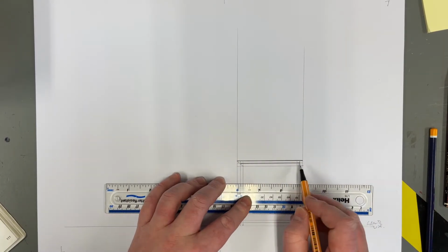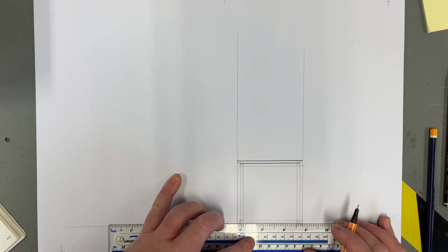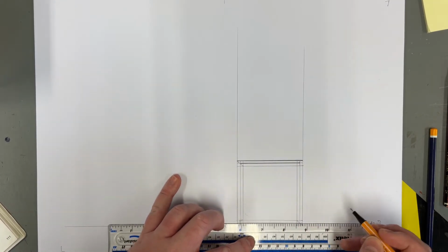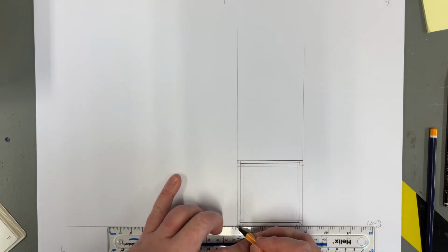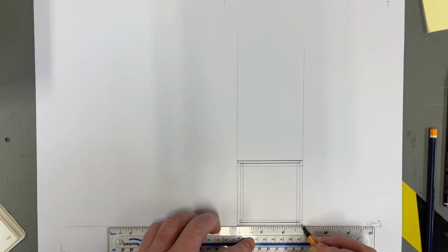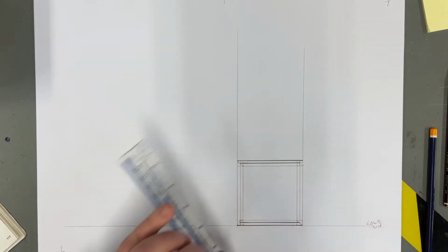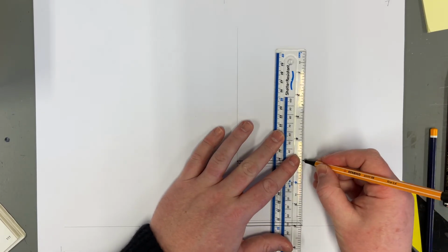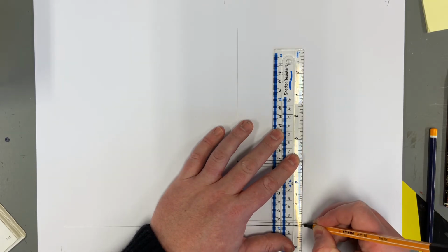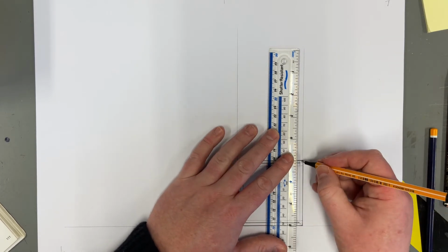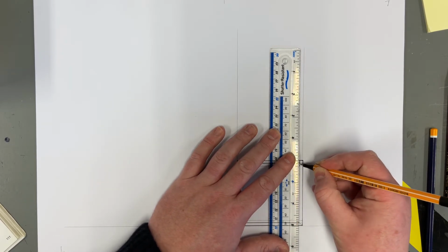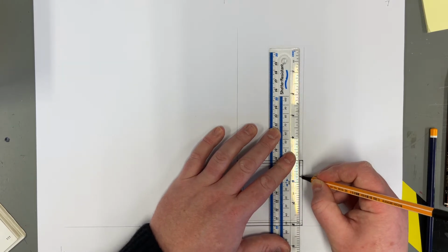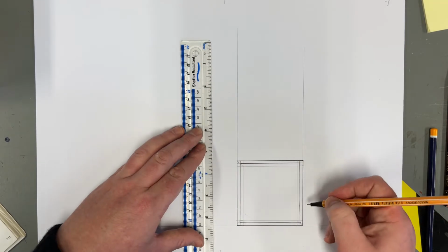So that's the top line of where the plastic would be. I'm going to jump down to the bottom. We wouldn't see this line here, that would be hidden behind the plastic, but we would see that line there. And then on the ground line, we would see that line there. On the right hand side, we obviously see the edge of the birdhouse carcass. Next one, this little half lap would come down, and then we sketch the rest of the line for the piece of plastic, and that would come down and connect to here.